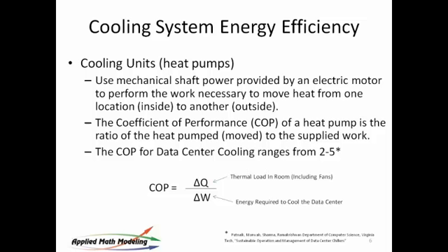You can do it while the machine's running, and you measure the current going to them on the 3 phases, and then you use standard equations to determine the amount of energy consumed, which is the average of the current going to the device times square root of 3 times the voltage. So it's fairly straightforward to measure.